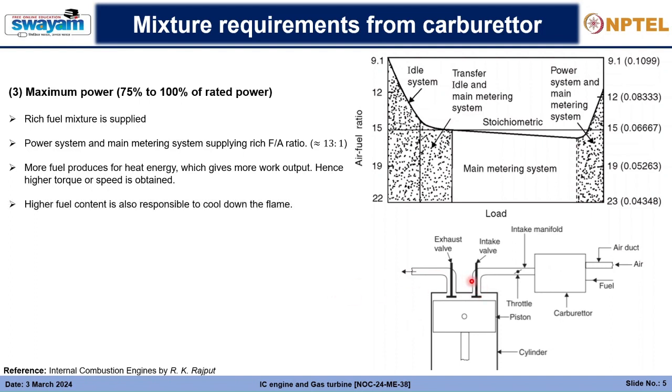So what happens is that higher fuel content is also supplied in the cylinder, which is responsible for cooling down the flame. Now, during very high power operation, the engine cylinder and the intake and exhaust manifolds become very highly heated up, and it may exceed its working conditions.